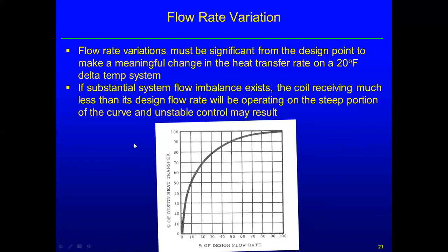Then you may have control issues, because a very small change in valve position results in a huge change in heat transfer, and that can cause unstable flow. That can be a problem. It's amazing that some of these systems work very well at all. It's not really as hard as some of this may make it look, but still a significant amount of information the designer needs to know and understand.